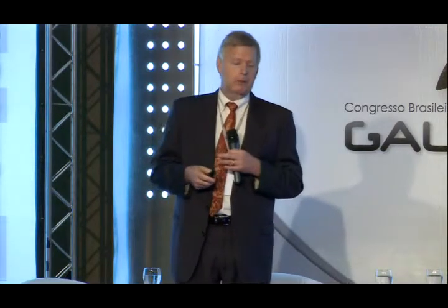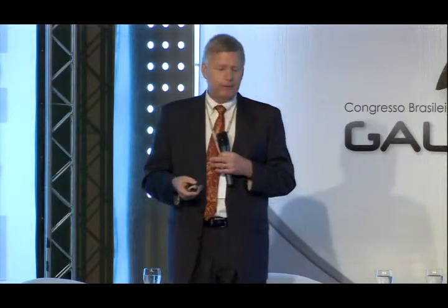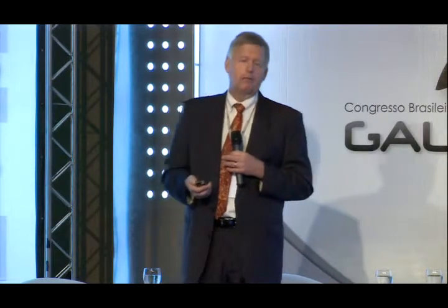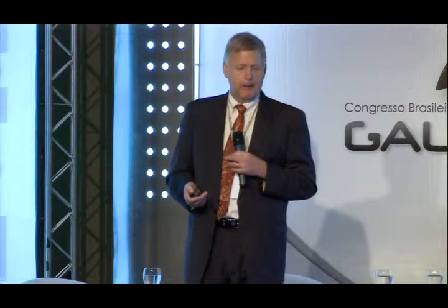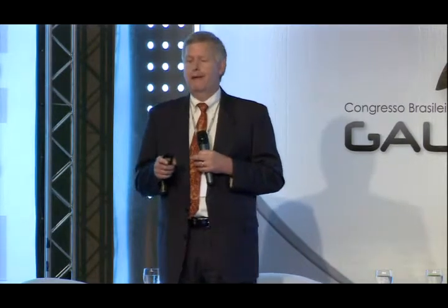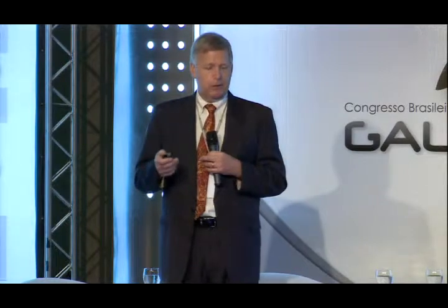If you go more expensive, then you have the more engineered systems, the more durable coatings. But remember that these are usually about 15-year lives for any of the paints. If you have 15 years, you are doing very well. We do have a much longer life with hot dip galvanizing. So even on a first cost basis, hot dip galvanizing is very competitive with some of these paint systems.